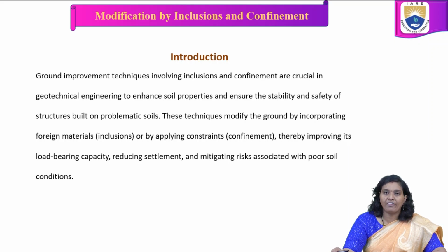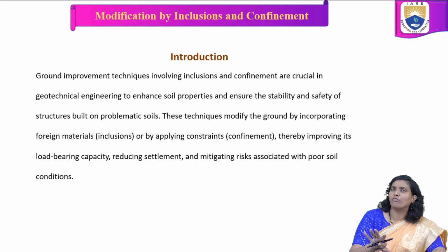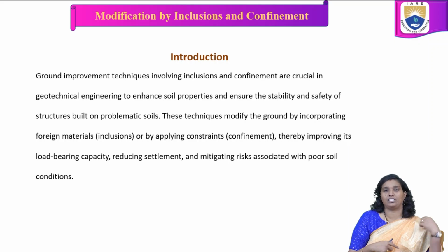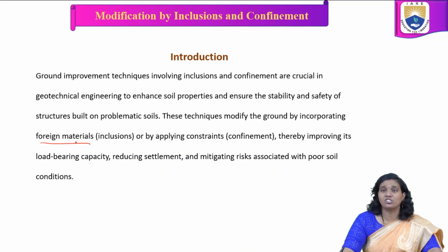These techniques modify the ground by incorporating different materials. It is not that foreign materials mean something other than soil; we are going to use materials with different properties, whatever they may be, to include in the ground. So that's the meaning of foreign materials. They work by applying constraints, that is nothing but the confinement, thereby improving load bearing capacity, reducing settlement and mitigating risks associated with poor soil conditions.